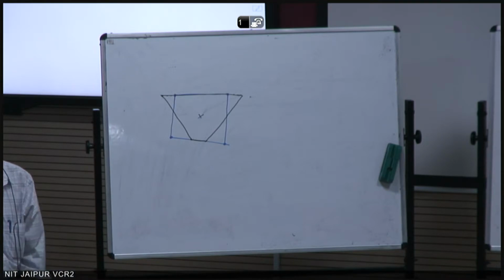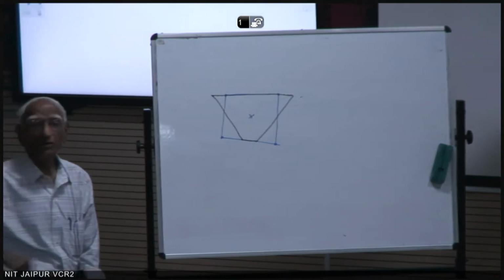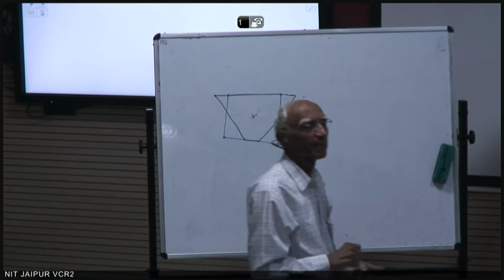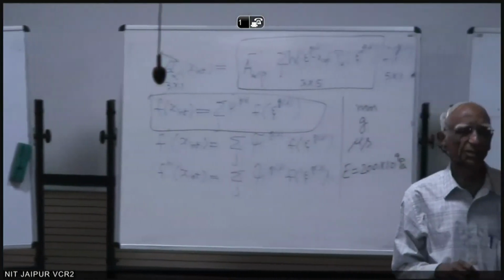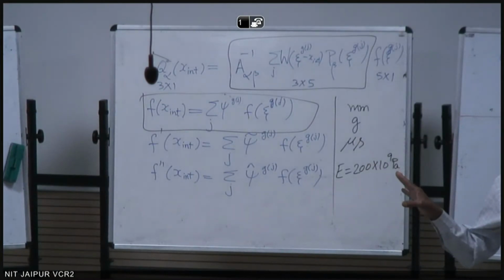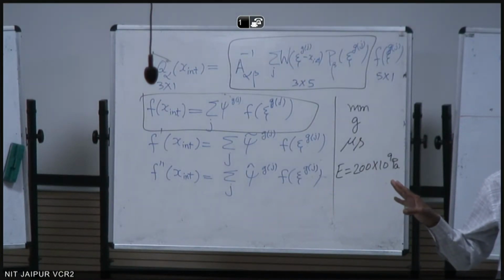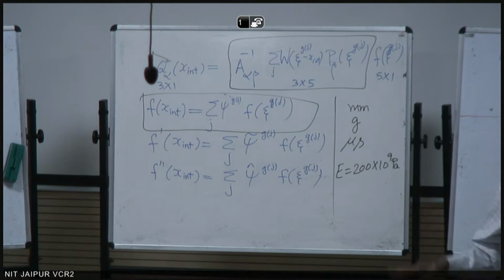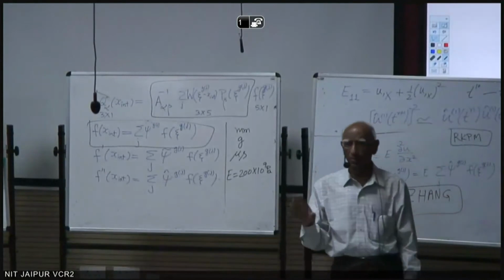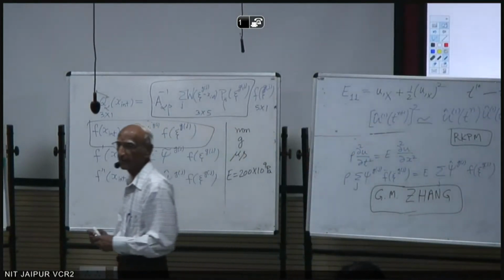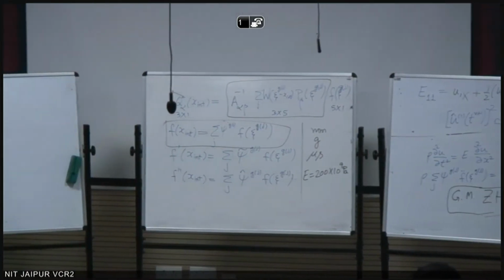0, very good. So if I am using a one-point integration rule, that rule says that you use your integration point at the centroid. So there is no energy used, even though the element has deformed. So these are called zero energy modes or spurious modes, and they create problems.